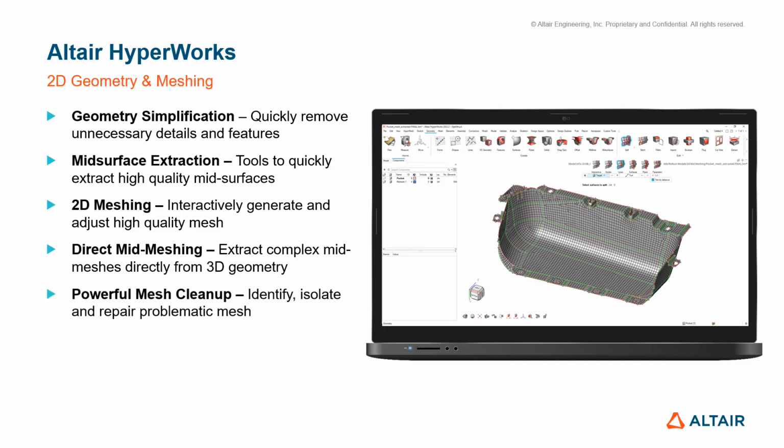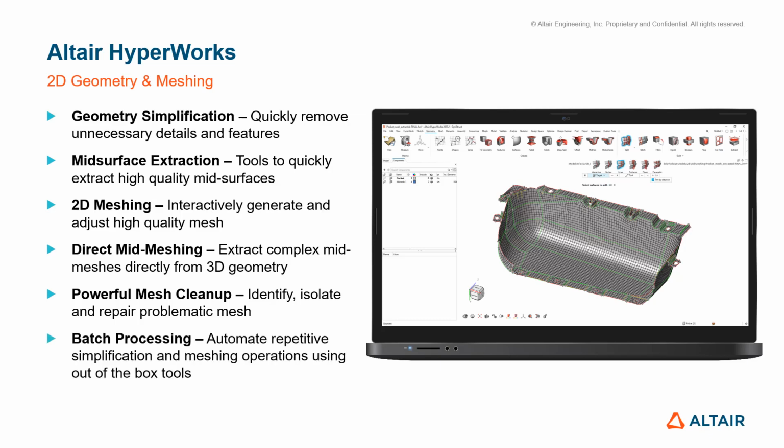We showed you cleanup, so the ability to identify, isolate and repair problematic mesh either manually or completely automated. And then finally, we looked at the batch processing tools available to either prepare geometry ready for manual meshing or to completely automate the geometry simplification and meshing process using our out-of-the-box tools.